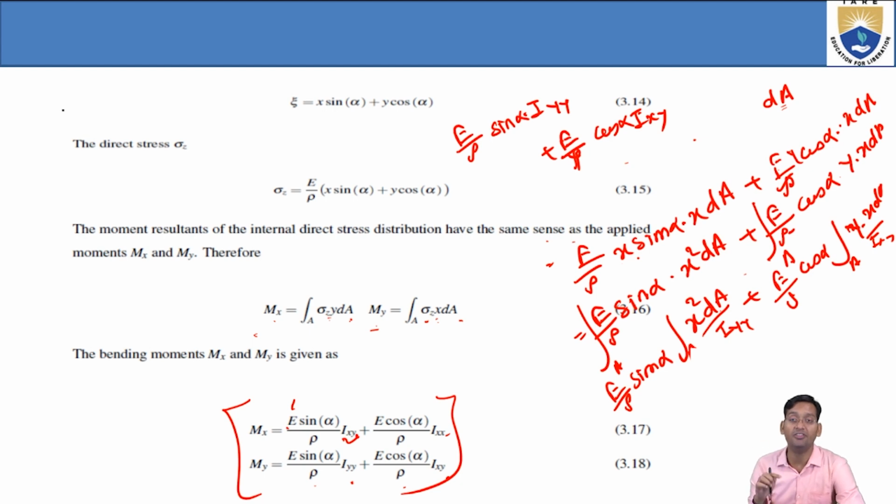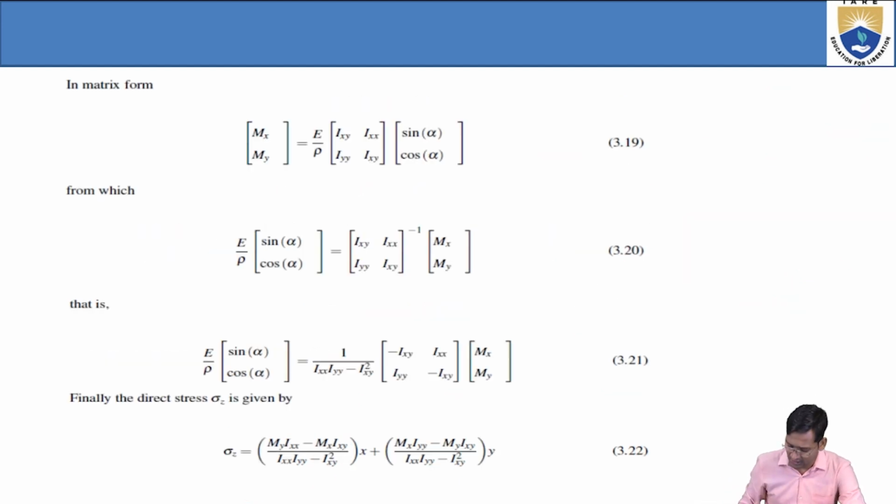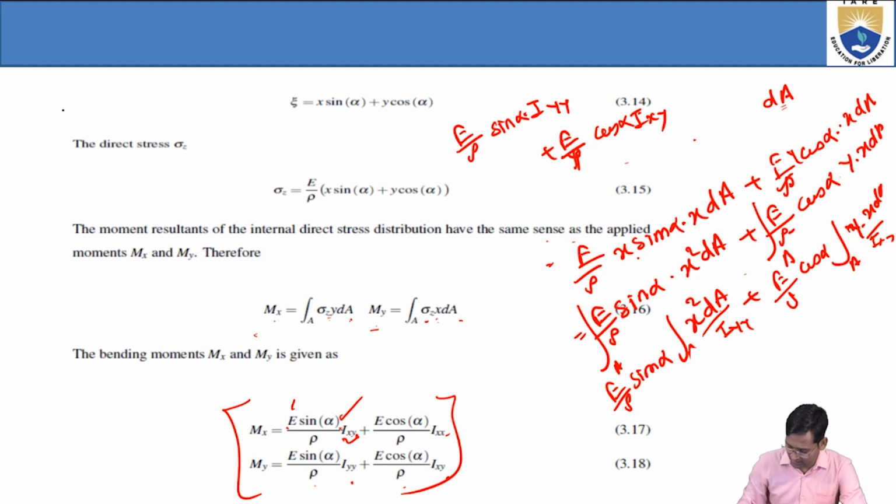That's why earlier we had seen that it adjusts by itself from 45 degree to 40 degree, 38 degree in case of other, because at 45 degree no wrinkle will be there. Both sides should be the same, so it's just adjusted less than that. For normal it's 40, but for aircraft structure it is around 38 degree. So according to the moment of inertia, the bending moment will be there along the x-axis and along the y-axis. Now the same thing written in matrix form.